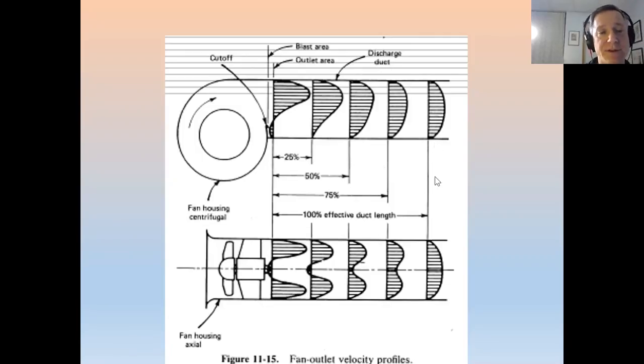The reason for this is the molecules are pulling each other along due to surface forces. That's viscosity. So if one molecule is going faster than its neighbor, it's going to drag its neighbor along due to surface forces. It's a viscous issue. That's the heart of how fluids behave. They don't travel alone. They travel with their friends, and they drag them along.